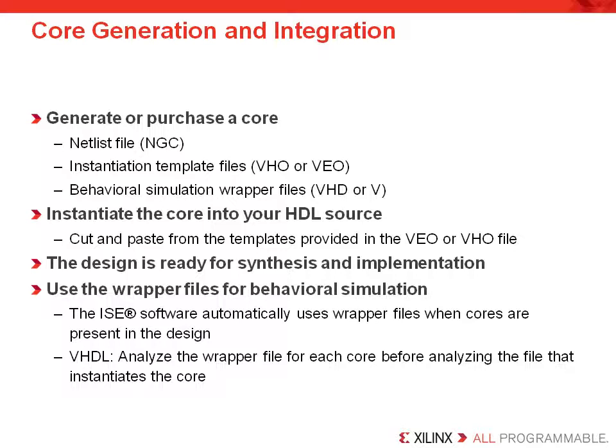During the first stage of implementation, the Xilinx implementation tools will read in the NGC or EDIF file that was created by the code generator software system. Again, if the core is not in the project directory, be sure to add the directory to the macro search path property of translate. If you are not sure what this is, go look for it in the command line user guide. Basically, it allows you to store your IP netlist in a separate directory outside of your project directory.